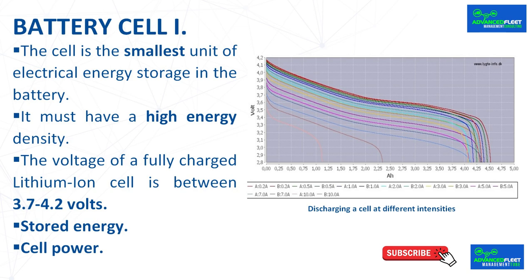It is common to sometimes give the capacity of a cell at a certain discharge rate. A perfect example is the Nissan Leaf, whose 3.8 volt cells claim to have 33.1 ampere hours. So doing the math, the Leaf has 192 cells divided into 48 modules, supplying a final 24 kilowatt hours. But that capacity is as long as they are discharged constantly at 0.3 C cell power.